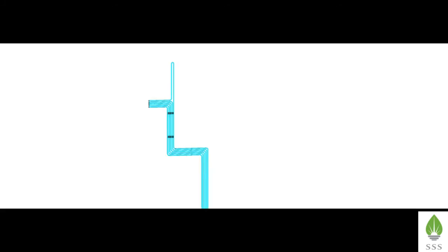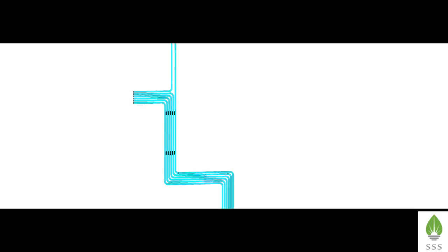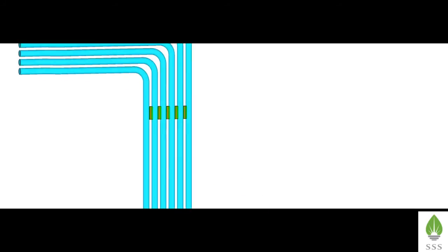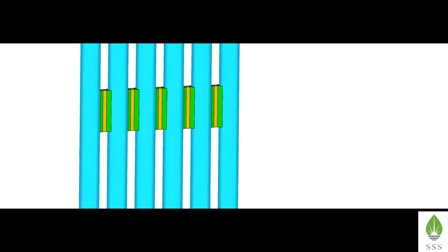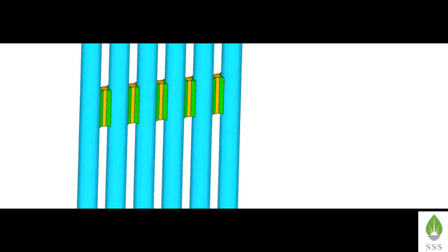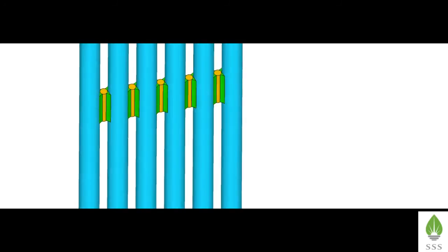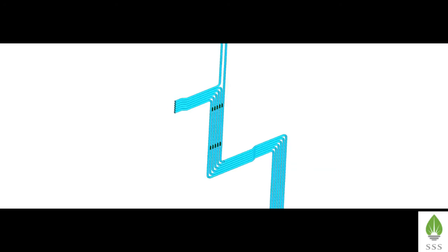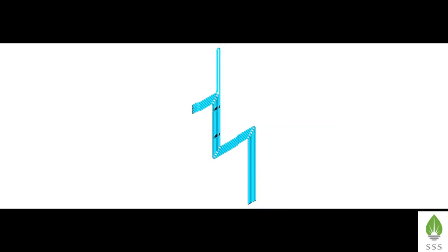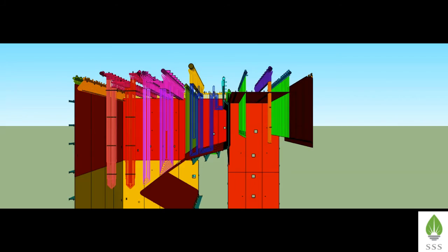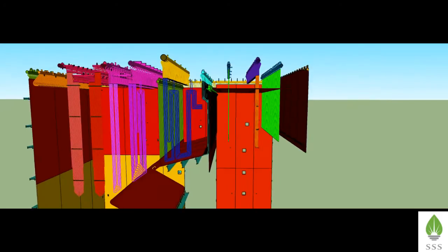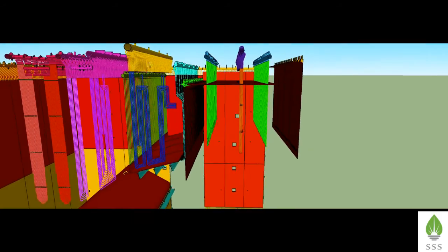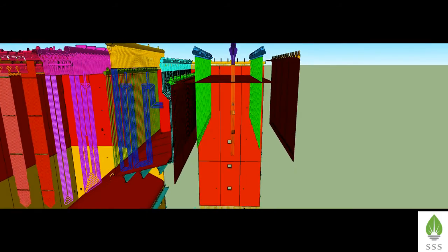Similar to primary superheater coil, reheater crossover tubes are also provided with the separators which maintain the pitch between tubes. Lift the reheater crossover tubes using the separators.